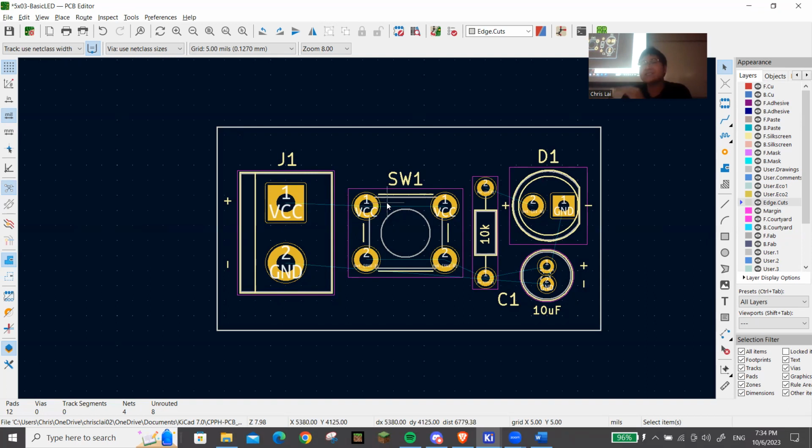So this is the simple version of PCB design. I'm not going to get into polygon pours. I'm not going to get into vias. That's for the more advanced stuff. But right now, all we're concerned about is connecting all of these components together. So we're going to grab the line tool and we're going to go on the front copper layer. For me, it's red, but for you, it can be green, orange, blue, whatever theme you choose. Yes? And standard PCB design is 2 layers.